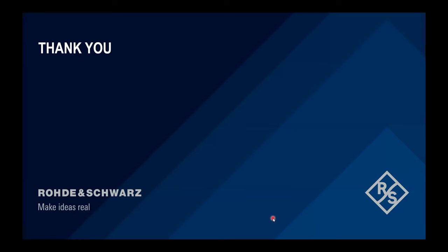This will all be something you could do at your bench, and this would be called pre-compliance analysis. If we're then pushing that to a higher level, then you'll need to be closer to the standards. Then you'll have the definition from the EMI standards of how the setup should look. You'll need a shielded chamber and so forth. It could become quite complicated and expensive, because at a certain point you'll need the measurement receivers, as well as the standard approved LISNs, and of course the EMI receiver at the end for taking these signals from the LISN or from the antenna.